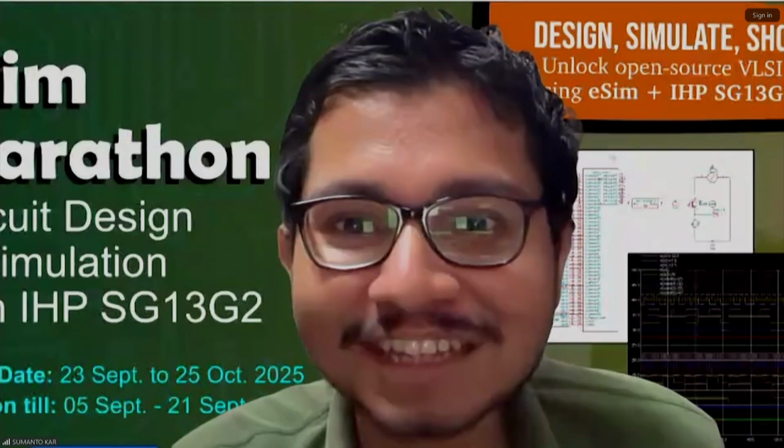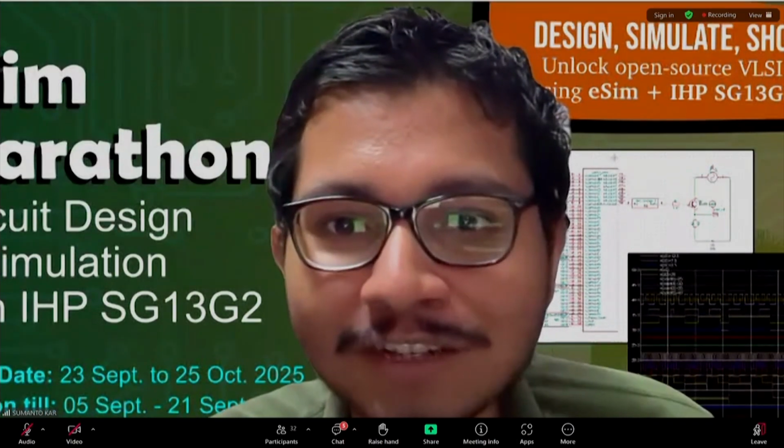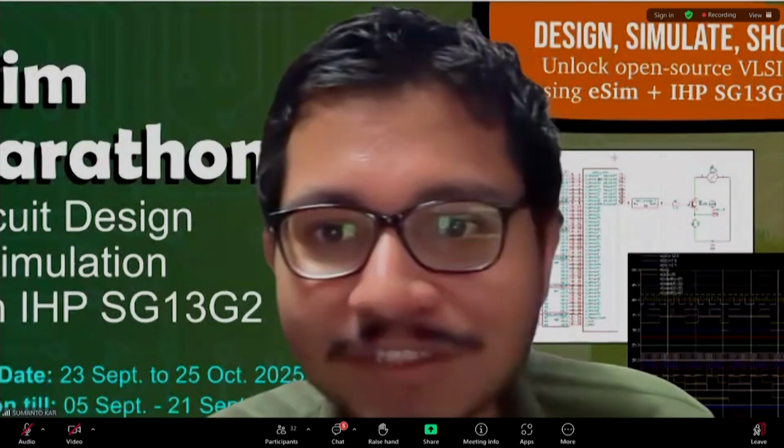One more question came in: how does Ngspice integrate device level models to accurately simulate power and energy behavior in MOSFETs? There is a very interesting thing here. If you talk about discrete MOSFETs, power MOSFETs, then you have to take power dissipation into account because devices heat up. When devices heat up, they change their parameters and their behavior. This is a feedback loop.